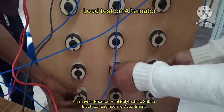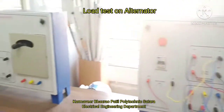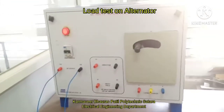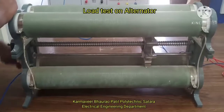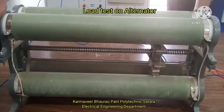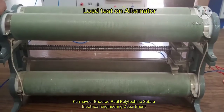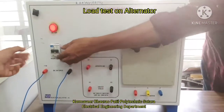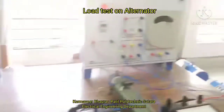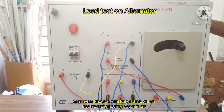Now we will make the load off. First we will make all the load off, then alternator off. Make the alternator excitation 0. Touch to the starter handle.